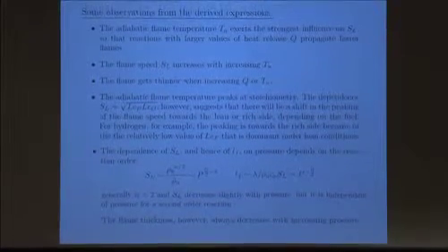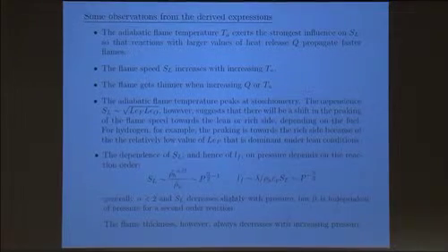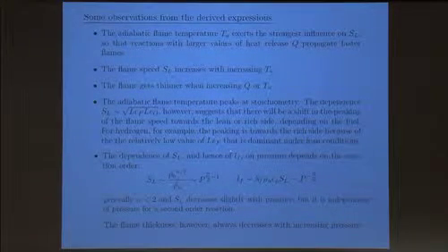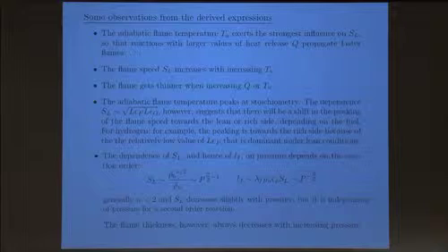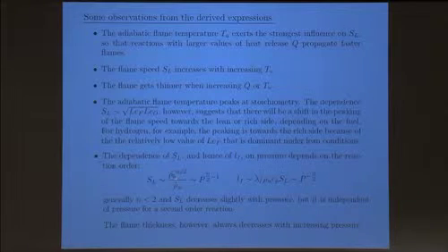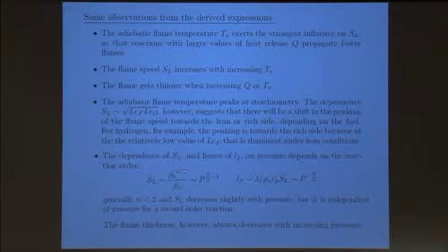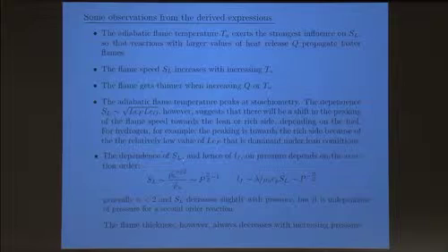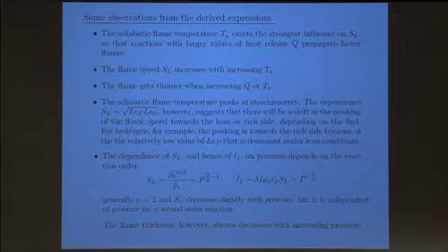Now let's see if there were some other comment that I missed. Yeah, so the next one is the dependence of the flame speed and therefore of the flame thickness on pressure. Well, the dependence on pressure comes because in the expression there was a rho burned raised to the n/2, where n is the overall reaction order, divided by rho u.